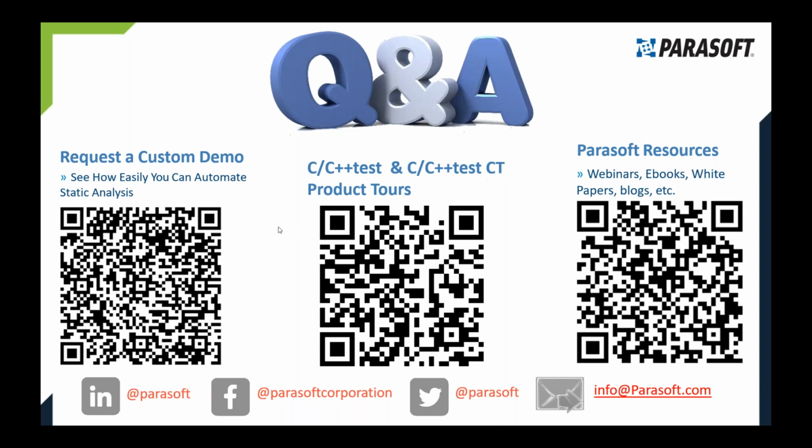So which exact objectives of DO-178C does the qualification cover? For instance, is the data flow analysis qualified? So, I mean, there are several objectives, and it's based on the DAL level. So if you have, say, DAL C, the objective says that you need to perform data coupling and control coupling, so data flow and control flow coupling. You have to do that. Those are the objectives that you need to do. I mean, yeah. So let's see, can we use FMEA for security?